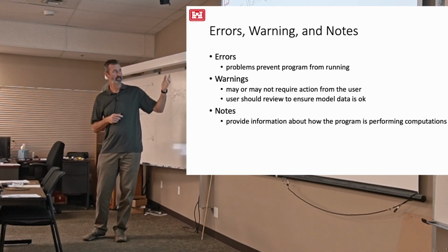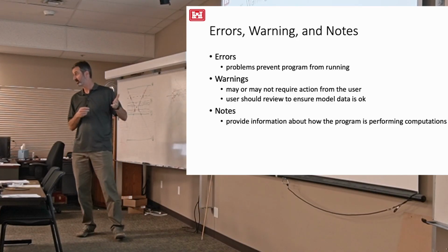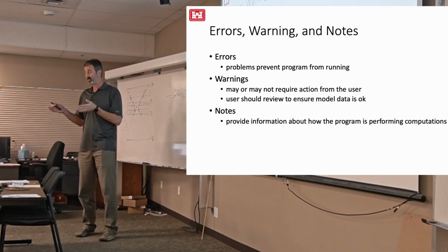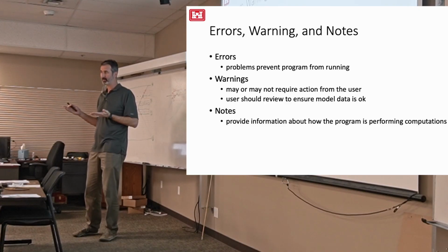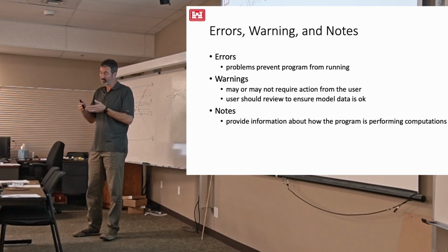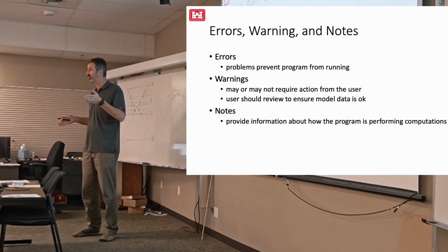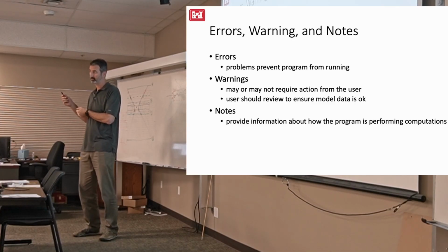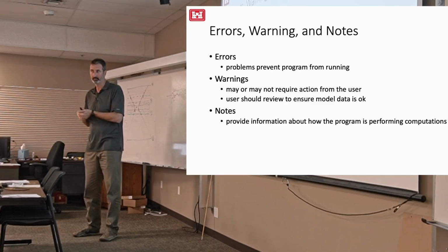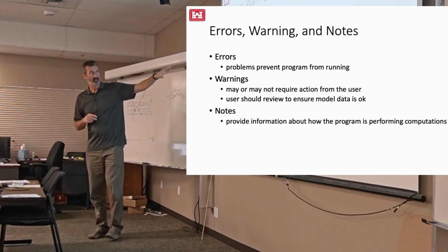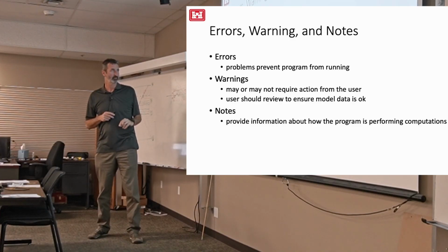Other problems, like you're doing subcritical analysis and you come to a point that's supercritical, the program could just stop and say, hey, this is not the right way to compute this problem, but we don't. We say, well, okay, you asked for a subcritical solution, but the real answer is probably supercritical. Well, we'll just default to critical depth for a while until it goes back to subcritical, which maybe never.